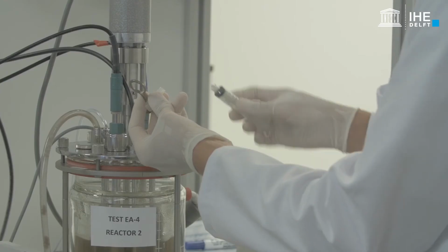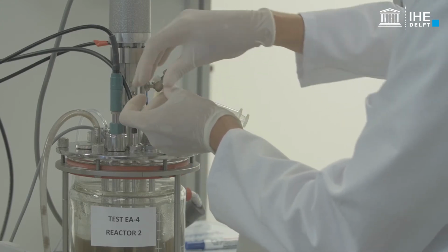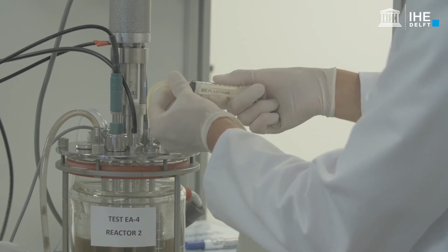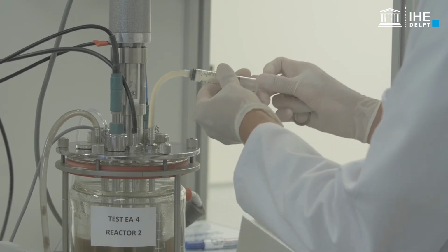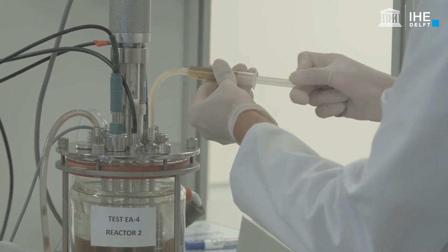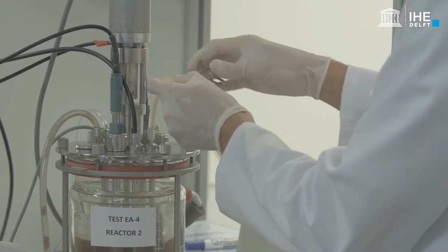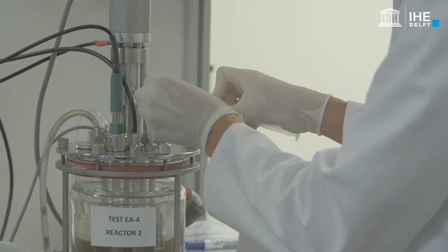These last samples for the determination of intracellular compounds and concentration of solids will be useful to determine the total conversions of these compounds in the aerobic phase. Meanwhile, the filtered samples will be useful to determine the conversions of the soluble parameters, in particular of orthophosphate.